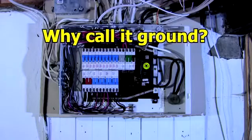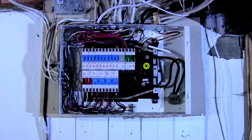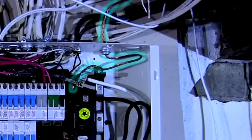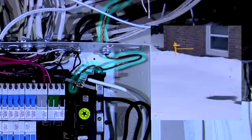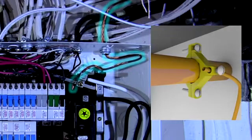But wait, none of that had anything to do with the earth ground. Why is the wire called ground? Looking at the breaker panel again, there's a thick ground wire connected to the neutral bar here that goes to a metal rod buried in the ground, called a ground rod, or to some other metal that's buried in the earth ground somewhere, like the metal pipe that brings cold water in from the city.